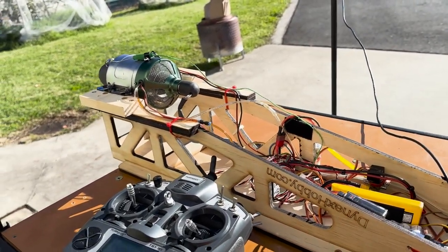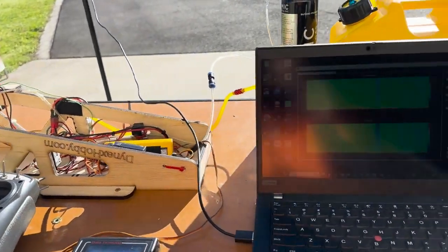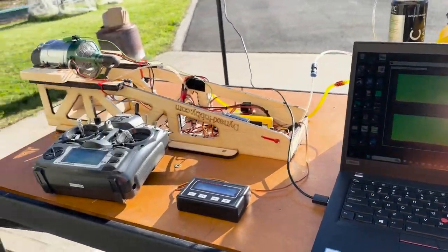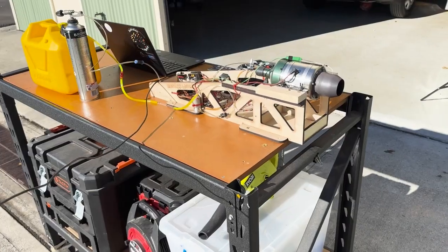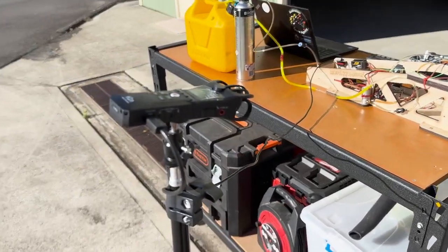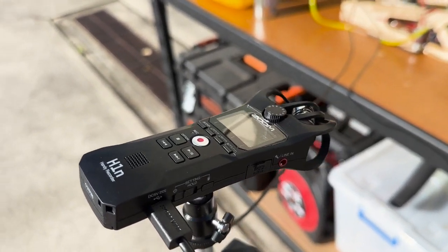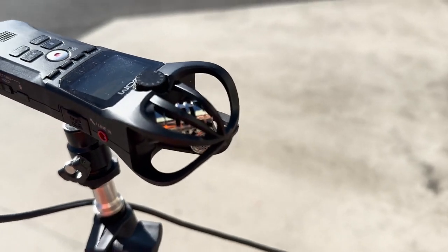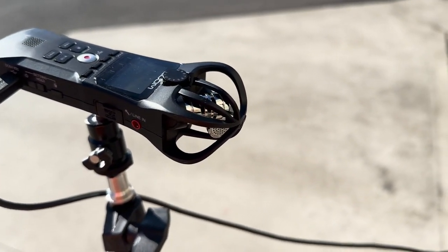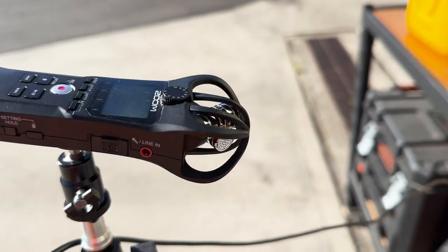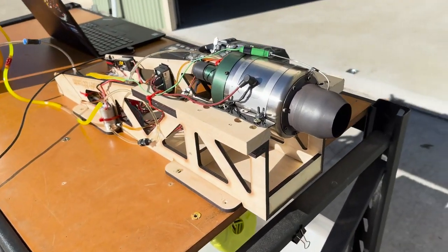Today I'm going to demonstrate how I can use a simple microphone attached to our PC to measure the vibration levels from a gas turbine. To do this, what we need is a USB microphone. In this case, this is a Zoom USB microphone. It's actually a stereo microphone. It's got two microphones which are directional, as you can see there. So there's the silver microphones, and they're pointing in the direction of the turbine.